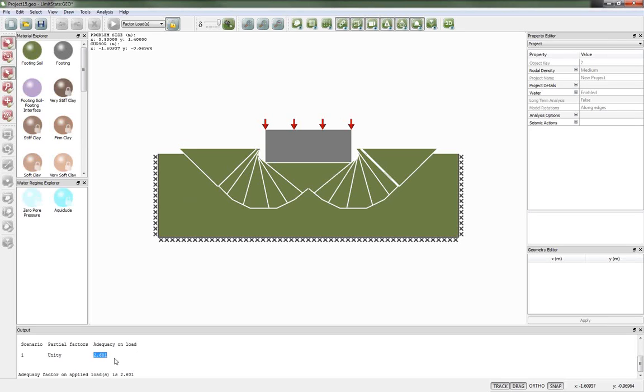So, if you like, this is a factor of safety on the load. It's telling us that we have to multiply that load of 100 kilonewtons per meter squared by 2.6 in order to get collapse. We could have worked that out using Terzaghi's standard bearing capacity formula. If you're familiar with that, the solution is 2 plus pi times the undrained shear strength. So that's 5.14 multiplied by 50, which comes out just a fraction below 2.6. So we get very close to that answer very quickly.